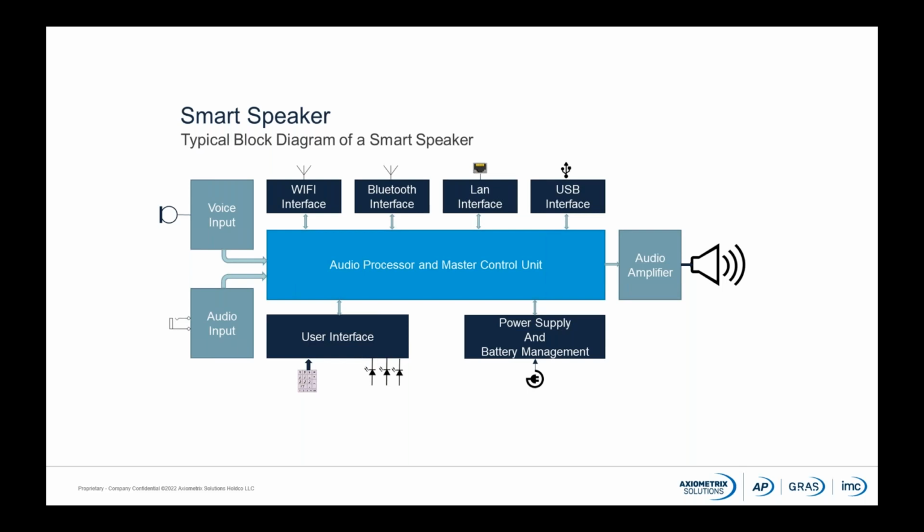Now that we've seen smart device signal paths from the outside, let's have a look inside the smart device. This block diagram shows various circuits or components within the device, which can each be tested for quality. Most of these components can be isolated and tested in closed loop configurations, although optional digital input-output modules may be required in the APX analyzer to support the necessary connections. More on this in a few slides.